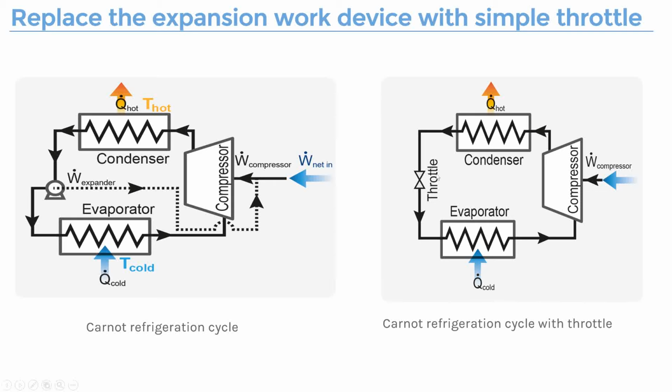But for this one, it's a type of expansion valve, and it achieves this function of having hot and high pressure refrigerant coming into this one and getting this very huge pressure release and becoming a cool refrigerant liquid state.